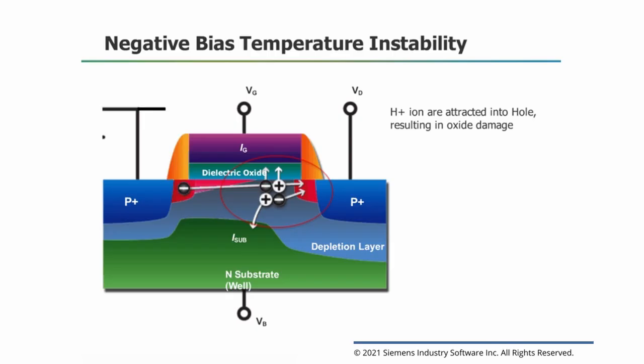Two main theories have been proposed to interpret NBTI degradation: reaction diffusion, or shortly RD, and the hole trapping/detrapping mechanism. The RD theory is the most accepted and explains the shift of the threshold voltage with the creation of traps at the interface between silicon and silicon dioxide in the presence of a strong vertical electrical field. These interface traps are generated by the dissociation of silicon-hydrogen bonds. Hydrogen comes from the oxidation.